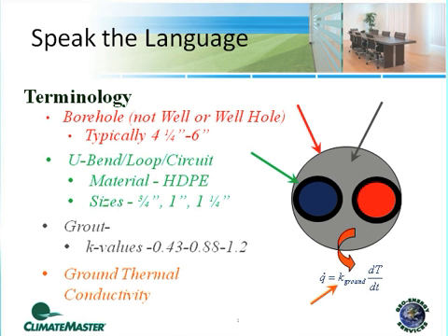There are 3 common pipe sizes that we put down into those vertical boreholes: 3/4 inch, 1 inch, and 1 1/4 inch. What's going to decide partly whether we use a 3/4 inch loop versus a 1 1/4 inch loop is the diameter of the borehole. So if a particular drilling contractor tells us that, based on the drilling conditions or his drilling experience in that area, he needs to drill a 6-inch hole, we are likely going to need to choose a 1 1/4 inch pipe.